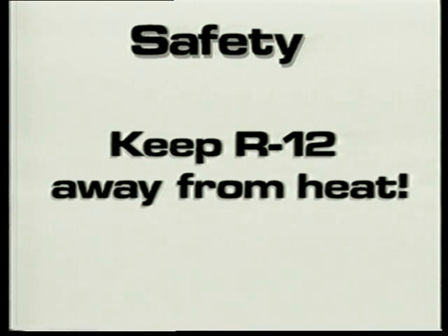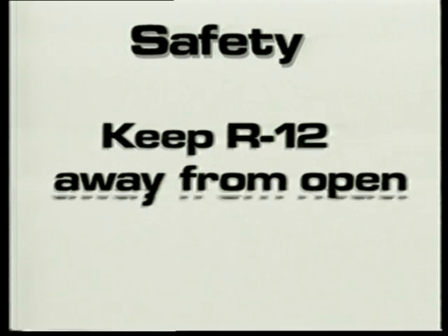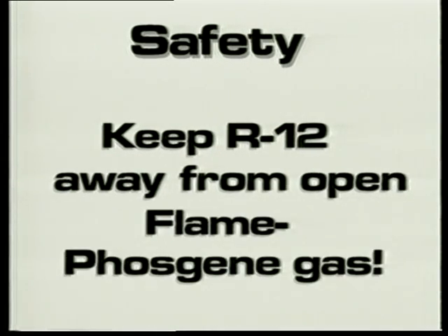Keep R12 away from excess heat. R12 containers can explode if they're heated by extremely hot water or by another heat source. Keep R12 away from open flames. When you burn R12, deadly poisonous phosgene gas is produced. Do not use older flame-type leak detectors in unventilated areas. Protect our atmosphere from harm. Never release R12 into the shop area. Use a recovery station.